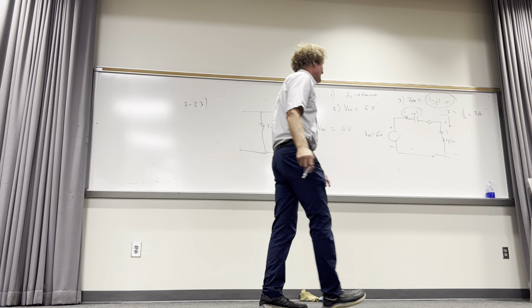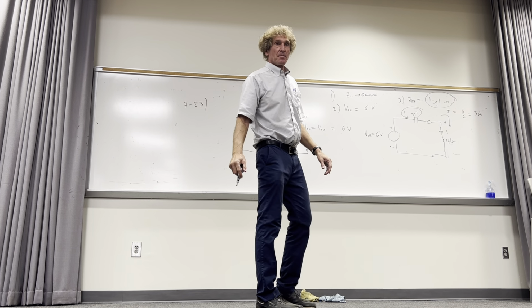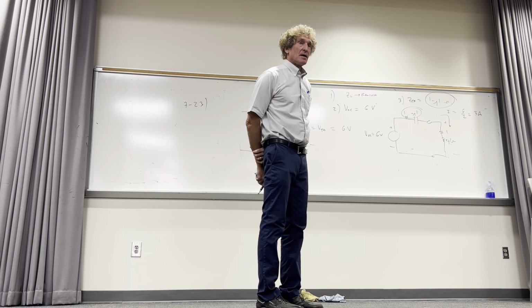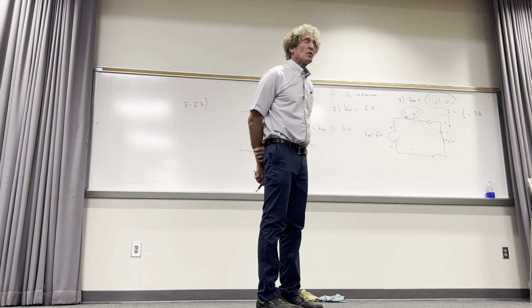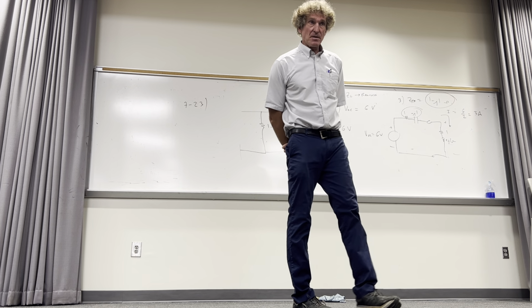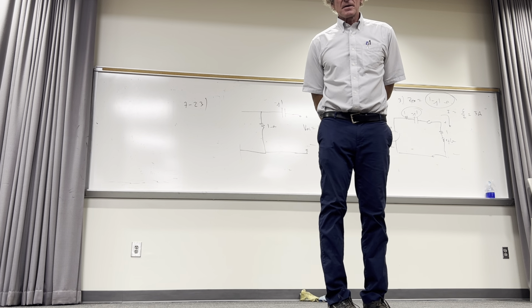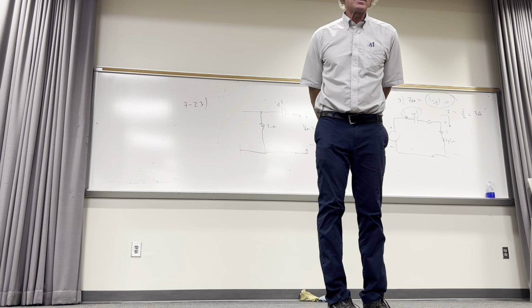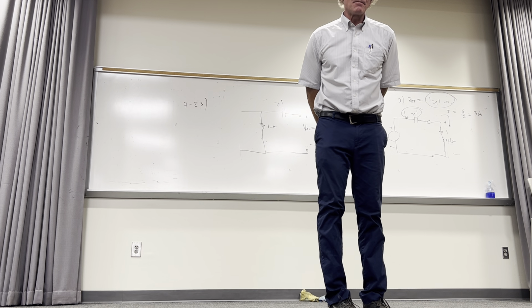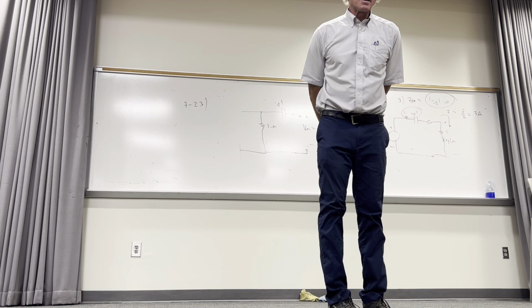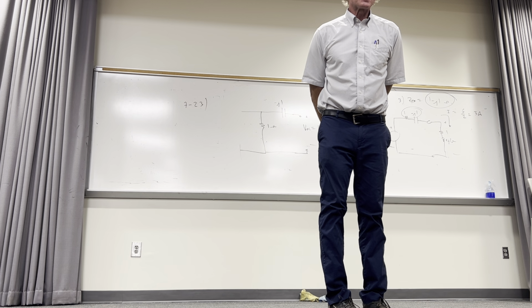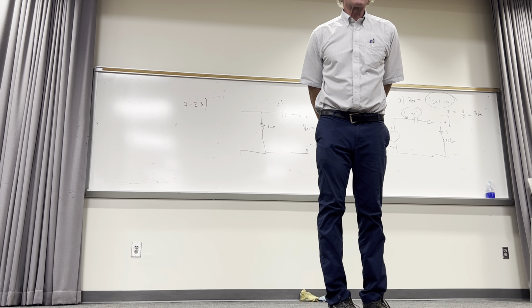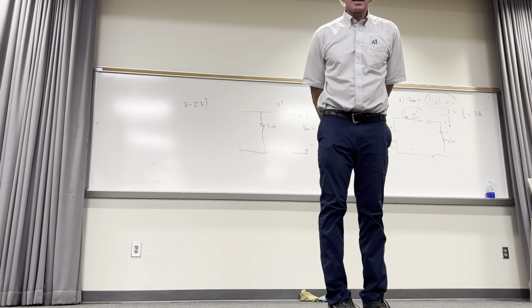Okay. Oh, I got one. So the conjugate there, or the 1 minus J1, is the Thevenin, right? It's the equivalent source impedance. It's the Thevenin impedance of the circuit. When we worked it, we had to get Z Thevenin and V open circuit, or V Thevenin. So you have to get the Thevenin equivalent circuit to do these problems. That's the idea.